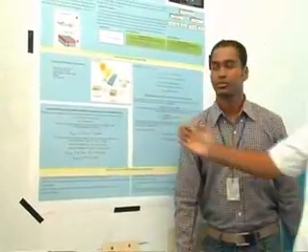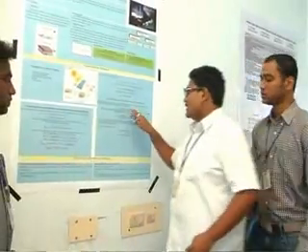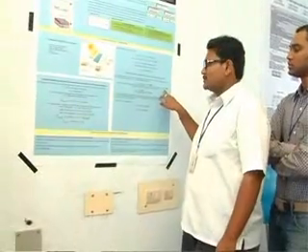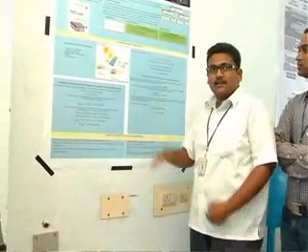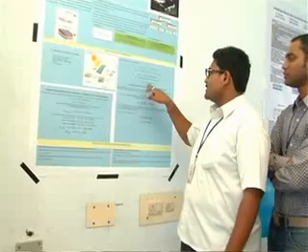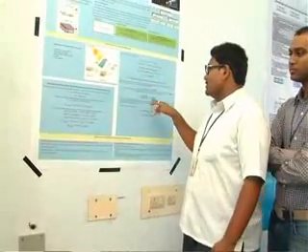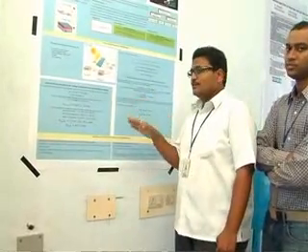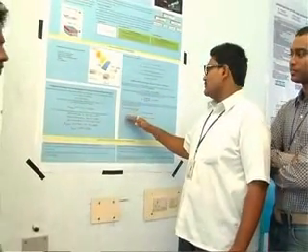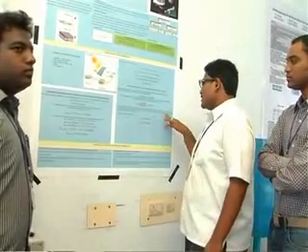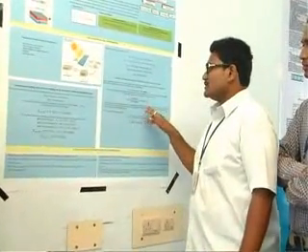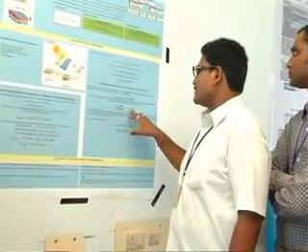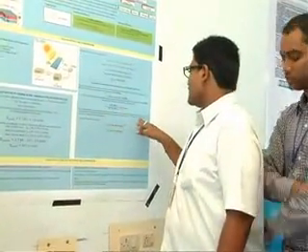Now, coming to the panels and the complete cost of battery, power and inverter, it costs around 1,40,000. But 1,40,000 can be regained by not paying the electricity bill of 34,342 per year, in just 4.07 years. So the net savings for the industry will be for 20.93 years, because for 20 to 25 years there is no maintenance cost for the solar panels. Subtracting 4.07 years, the payback period, you get around 20.93 years.